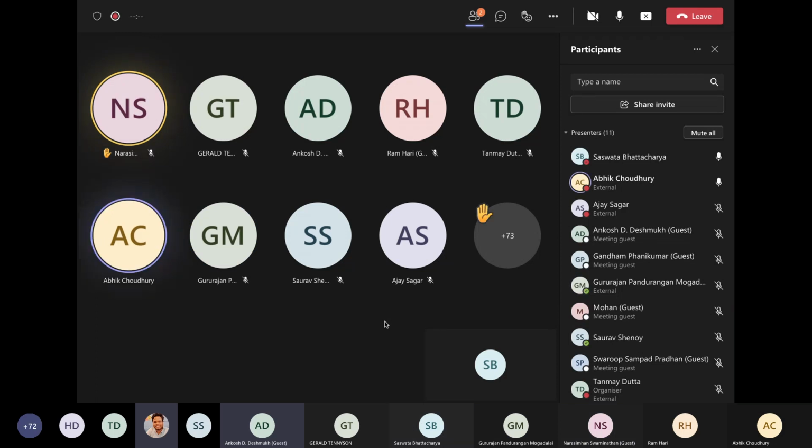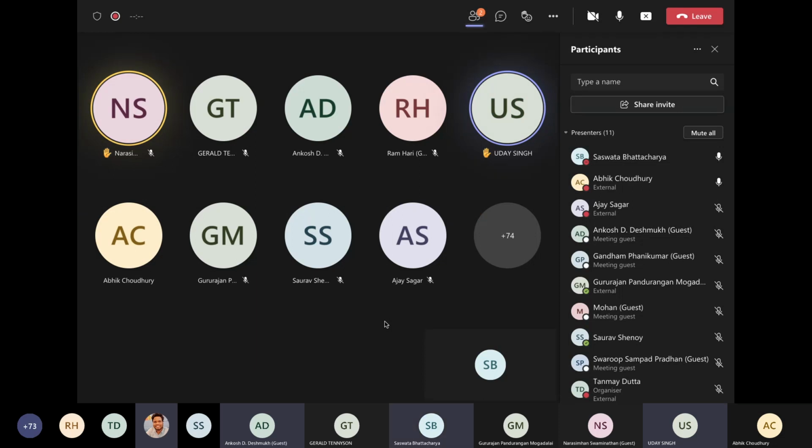There is Uday whose hand is up. Yes, sir. Can this model accommodate the bimodal precipitation? That's a very good question. This is still isothermal, but as Avik also wrote in his paper, if I include the slopes and temperature dependence, then we can do continuous cooling type of transformations, and also step changes. I can also do bimodal precipitation. Yes, it can do bimodal.